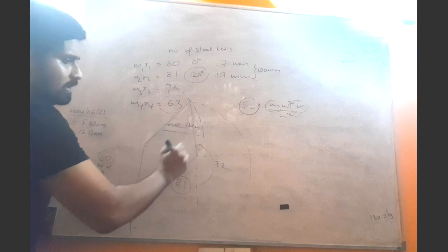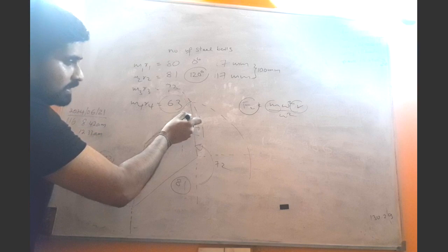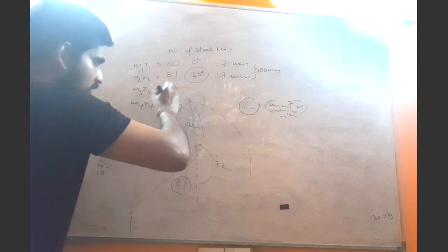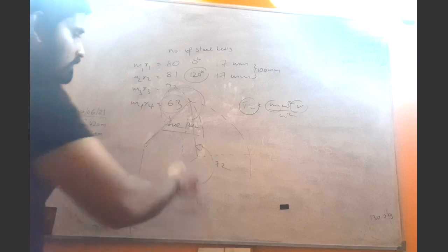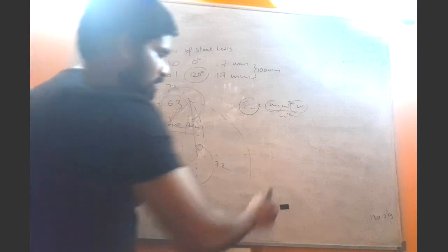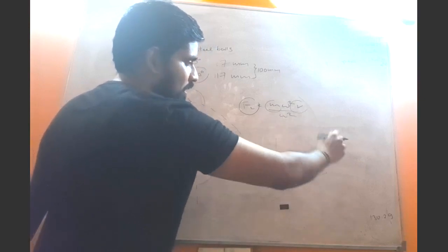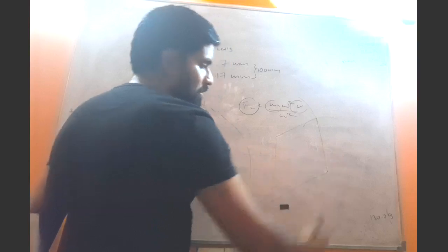Sketch this downward vertical, right? Again start measuring from this downward vertical up to here. So this particular angle represents the angular position of the fourth mass, right? Got it? If it is not clear, now this part we know, right? From here an arc, from here an arc, connect these two, right?